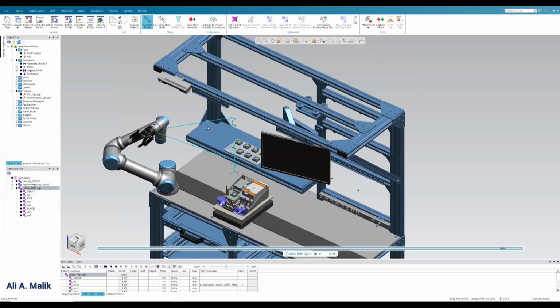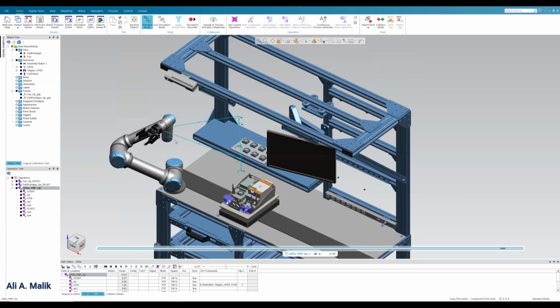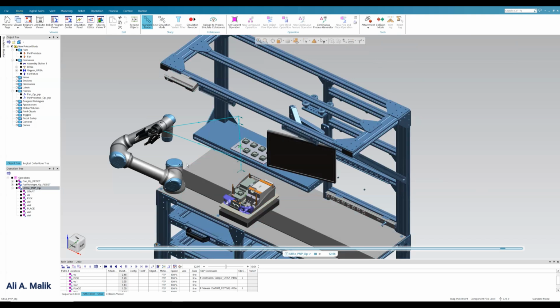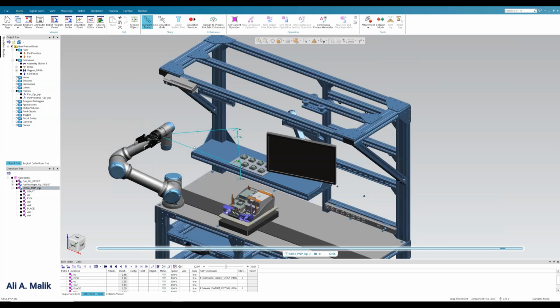Basically, it is more important that you should be able to relocate the objects, create operation, and use path editor to refine the operation. One more important thing is that now you know what is point-to-point motion and linear motion. Because it is a small robot, you have not probably observed that for all the motions, the robot has used point-to-point method. But if it would have been a large robot, you could observe that many times the robot is following a circular path while it is not needed.